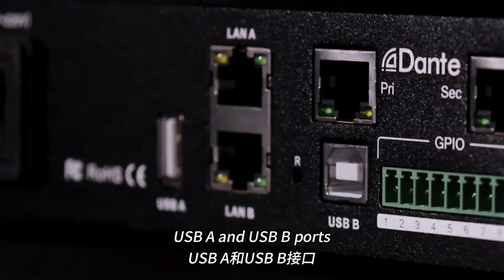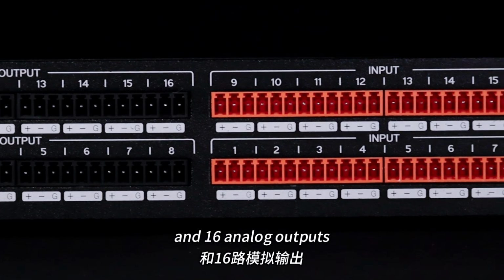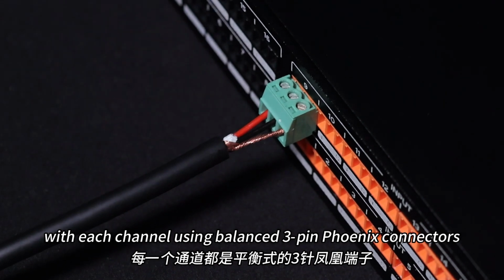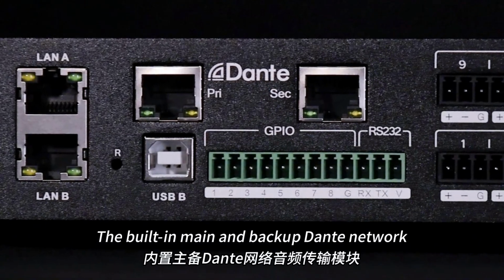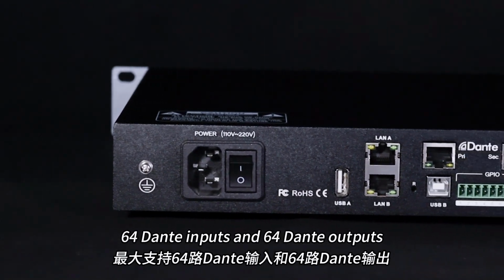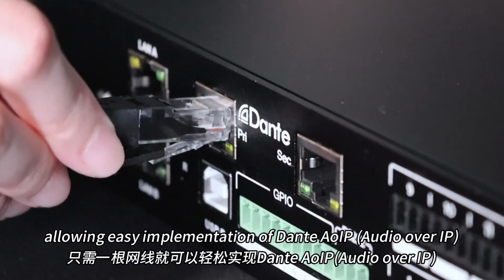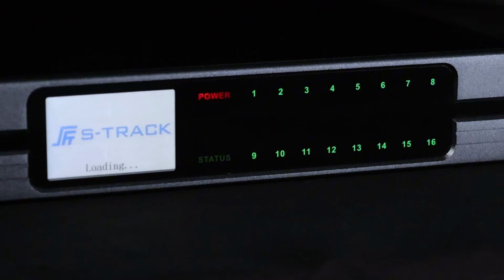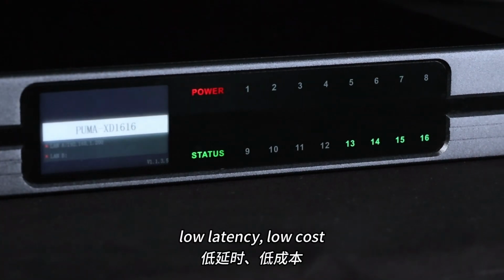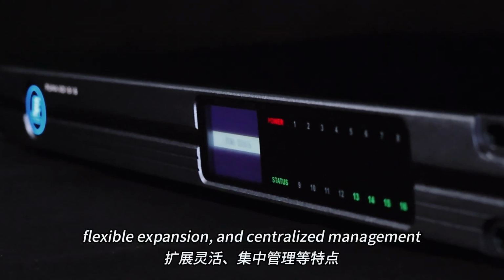USB-A and USB-B ports. The system supports a maximum of 16 analog inputs and 16 analog outputs, with each channel using balanced 3-pin Phoenix connectors. The built-in main and backup Dante network audio transmission modules support a maximum of 64 Dante inputs and 64 Dante outputs, allowing easy implementation of Dante AOIP with just one network cable, featuring high bandwidth, high fidelity, high compatibility, low latency, low cost, flexible expansion, and centralized management.